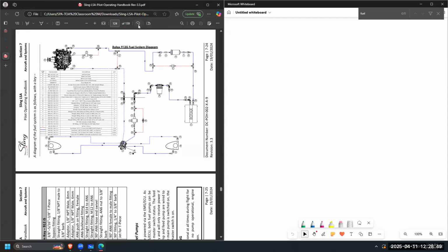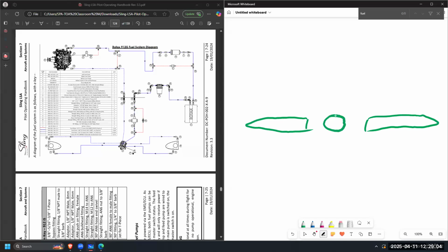So in the IS system, you have this one wing, two wings, fuel selector, either left, right, or off. This is the first filter, correct? This is your strainer. Then it's going to run into what? What's the next step?